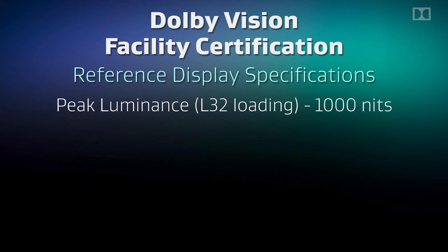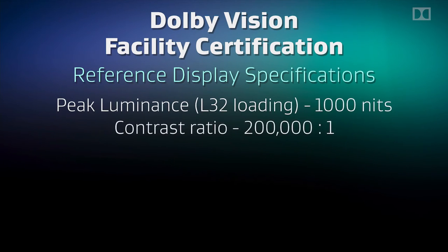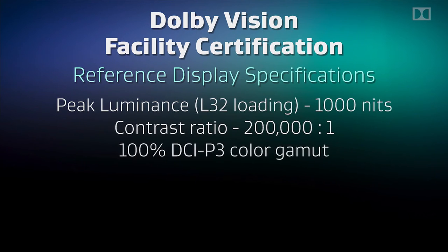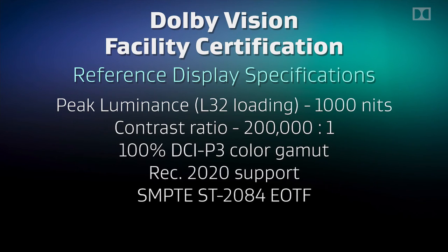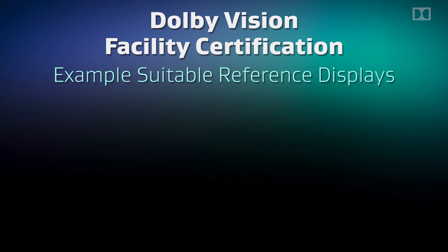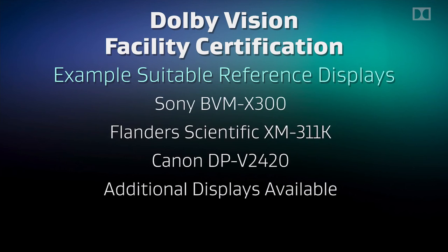First, a minimum peak luminance of 1000 nits on an L32 loading pattern. Next, a minimum contrast ratio of 200,000 to 1, and support for 100% of the P3 color gamut. You'll also need support for Rec 2020 and the SMPTE ST2084 EOTF. For this training, we're using a Flanders Scientific XM310K. Other monitors available at this time include the Sony BVMX300, Flanders XM311K, the Canon DP V2420, as well as offerings